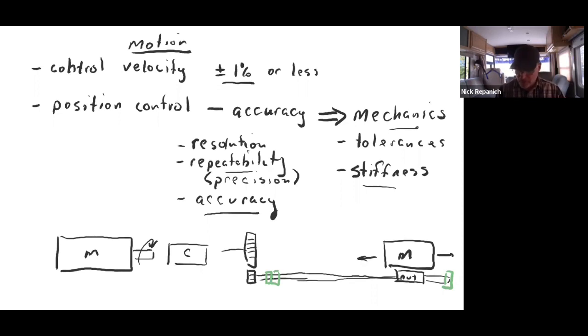Simple little system. As we begin to look at what we're really trying to control, ultimately, is where this mass is. But along the way, the problem is, in order to control that mass, you had to move this mass, which had to be slid back and forth on a lead screw. And that had to somehow be coupled or attached to a gear, which now had gear slop to another gear, and then was on a couple of shafts, which have rotational deflection.